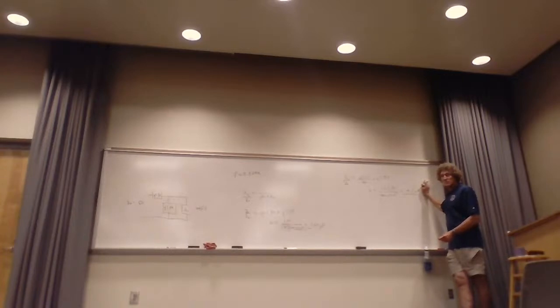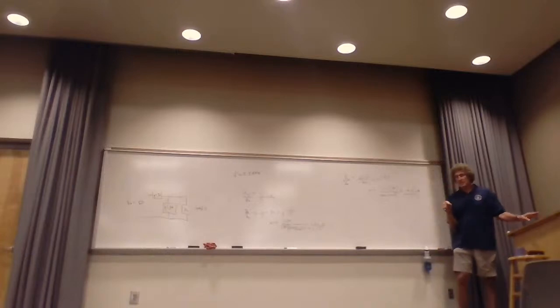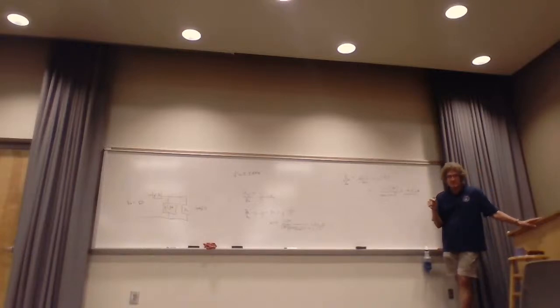I don't know if Stu chose these numbers on purpose to show you these things. That's a reasonable value, but when you're dealing with stuff that small, spend some time, get on YouTube or just Google it, high frequency engineer. You have to use dielectric screwdrivers. You try to get those lead lengths as absolutely small as possible. And the last trick I'll tell you, in case you ever have to build these things, anytime you can get